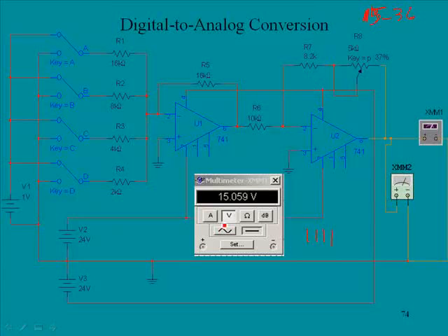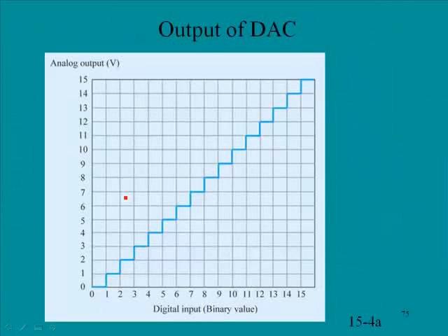And so this is a very basic digital to analog converter. So we come in with a digital value, and our output is going to be an analog voltage. And notice that this is only 4 bits. So we have this 15 volt possible output, and we have broken that into 15 individual possible outputs. And on the next screen here, this would be the sampled output, and you'll see here we have one-step increments, and this would be binary 0, 0, 0, 0, and this would be binary 1, 1, 1, 1.